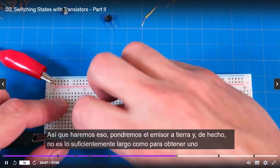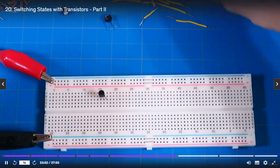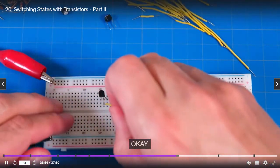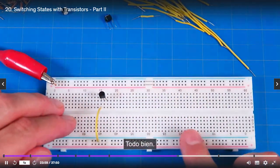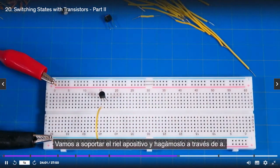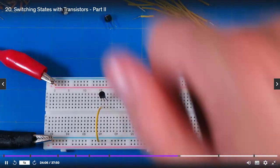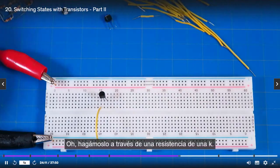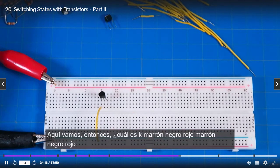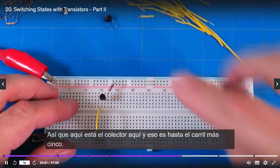And actually, that's not long enough. Let's get a longer one. Not too long. Okay, so we'll put the emitter to ground. Great. All right, the collector we're going to put up to the positive rail, and let's do that through a 1K resistor. Let's find a 1K resistor over here. Here we go. So what's 1K? Brown, black, red. Brown, black, red. All right, so here's the collector right here, and that's up to the +5 rail.